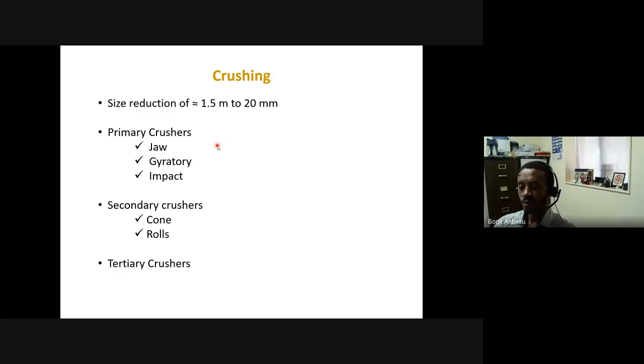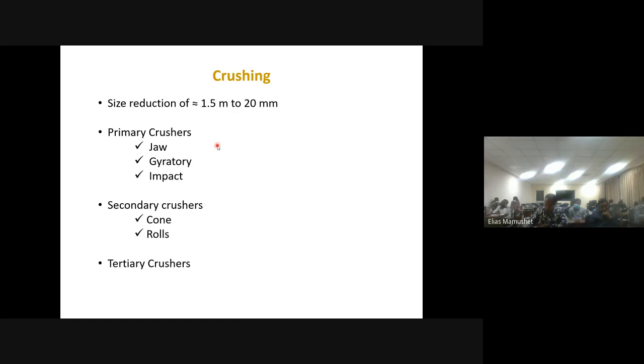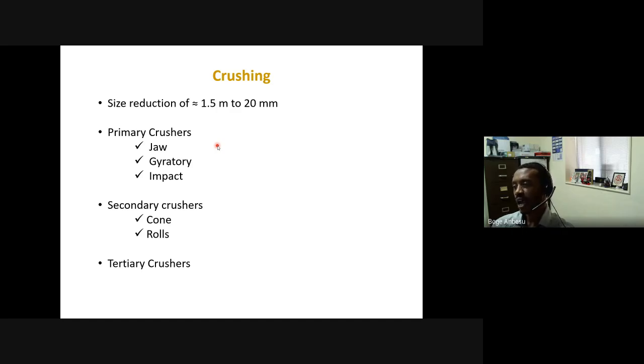Because all I need to do is to say, I want to produce less than 100 millimeter particles, and then I can feed this to my grinding mill. Whatever is under that less than 100 mil, maybe majority of them are under 50 millimeters, I do not really focus too much on that. I just focus on the top size or the largest rocks, because what I want to do is feed this into my grinding mill. Then all I want to control is the largest rocks or the top sizes. So this classification is based on the purpose of crushing and how that can be used.